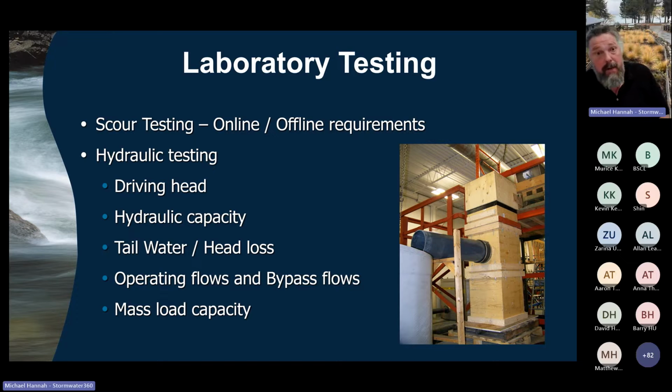And when you're putting a device online, what's really important is the hydraulics. So it allows you to develop empirical relationships for the head loss and the hydraulic effect, the driving head, the tailwater, the bypass flow capacities. And there are even laboratory methods for looking at the mass load capacity, or how long it will take before a filter clogs.